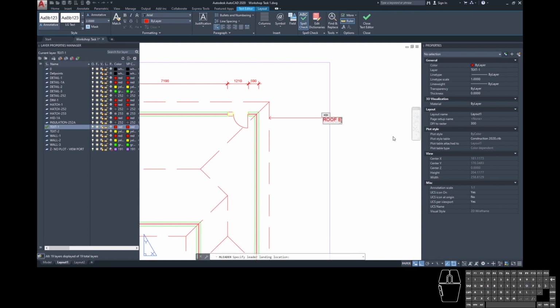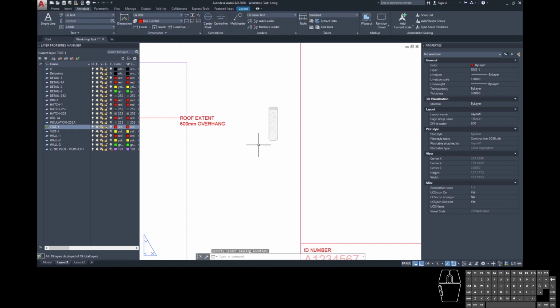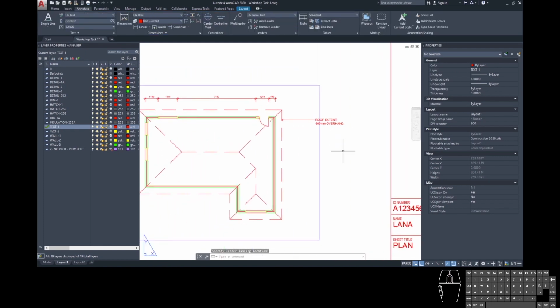All of your text should be in capital letters, remember, with architecture, except for units, which are allowed to be in lowercase. Now, the thing about the multi-leader is that this is multi-line text here, so this will just continue to do a very long single line if you continue to type. If you grab these little arrows and pull it out, it will automatically start creating little paragraphs for you. When you're done, you can just click away, and then we've got our multi-leader there.